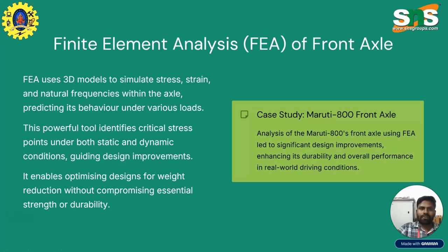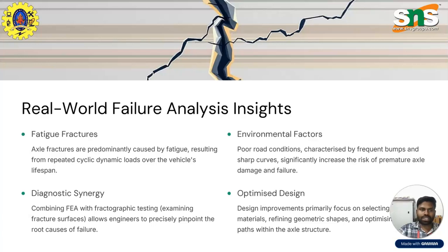And finite element analysis is a simulation model used to apply the impact of these loads, and we can visualize the actual stress, strain, and frequency change with a simulation of each component in the front axle, so that based on that, we can design or modify the front axle structure.